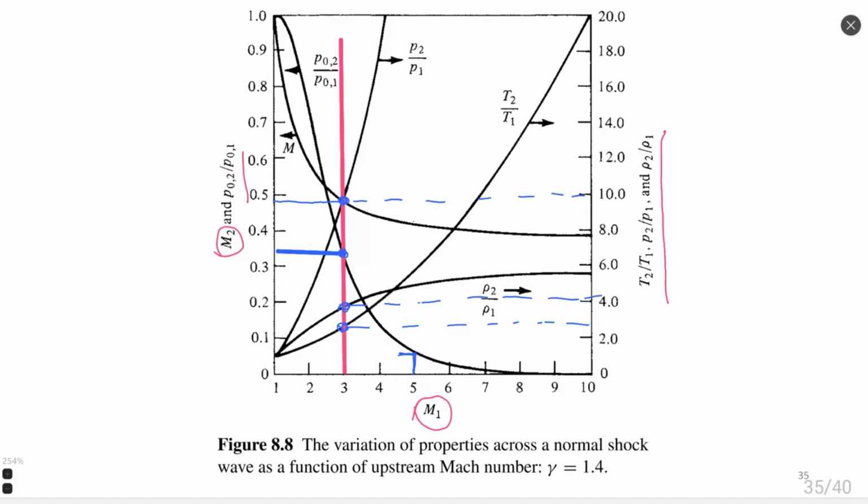This is why it's so challenging to fly in hypersonic conditions, because you have a significant reduction of efficiency, and you need to invent other ways to keep the energy in the system, in particular by construction of a complex diffuser that would gradually reduce flow velocity, and in such case losses are not so high.